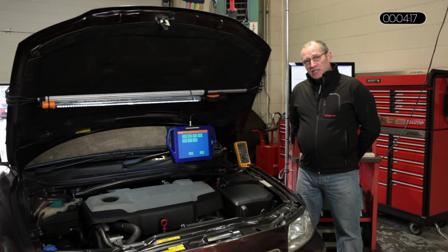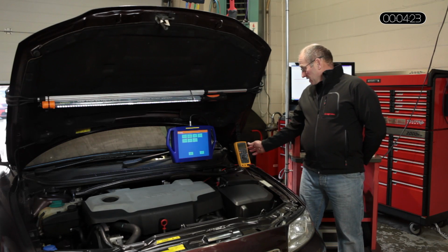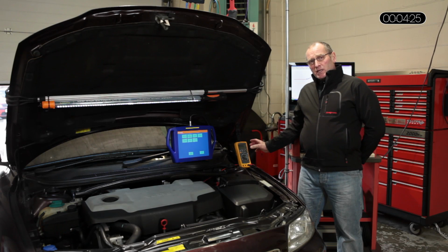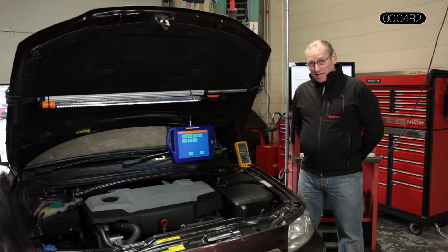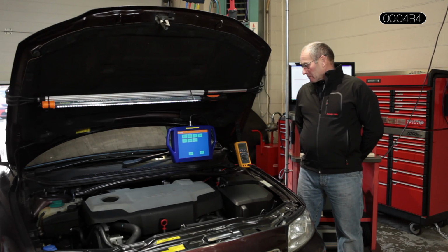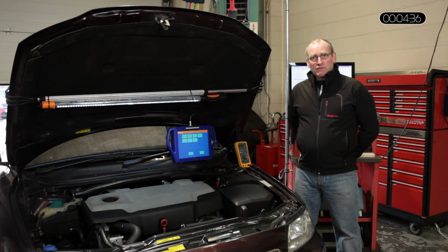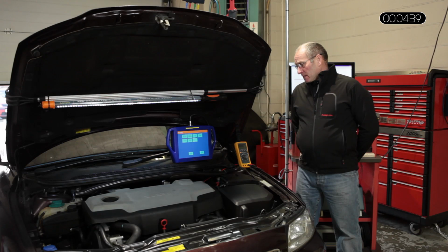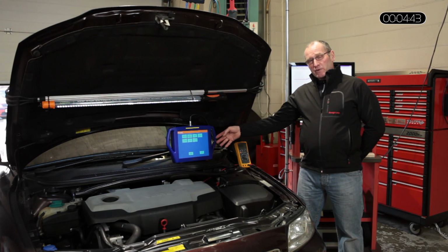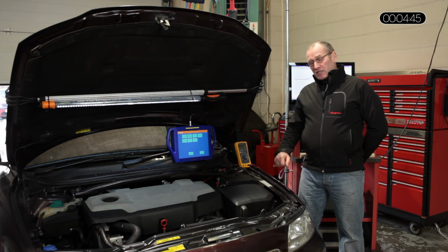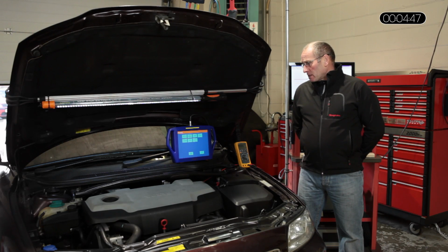But I wanted to look at the calculated value from the DPF sensor, and we also connected up the multimeter at the same time. The multimeter is a very simplistic way of proving a blocked DPF, or shall we say a sensor reading error. Let's term this quite carefully. A sensor reading error is simply looking at voltage, and in this case we did both. I wanted to see the correlation, the relationship between the serial data and the digital multimeter.